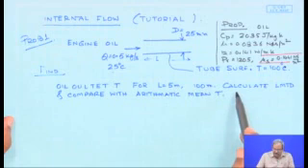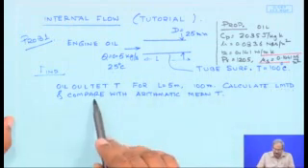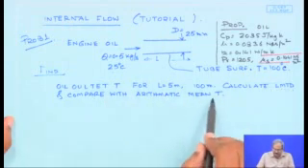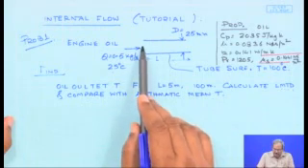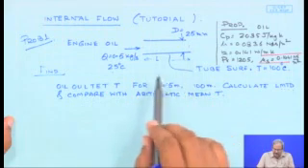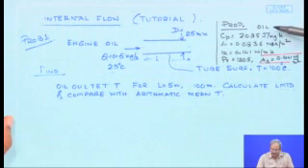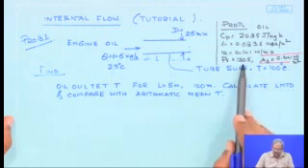We are also asked to calculate for each of these cases the log mean temperature difference and compare the value of the LMTD with the arithmetic mean temperature, that is, the arithmetic mean of the temperature at the entry and the temperature at the exit, for the two values of L, 5 and 100. The relevant properties for oil are also provided. The heat capacity is given, the viscosity, the thermal conductivity, and the Prandtl number for engine oil.